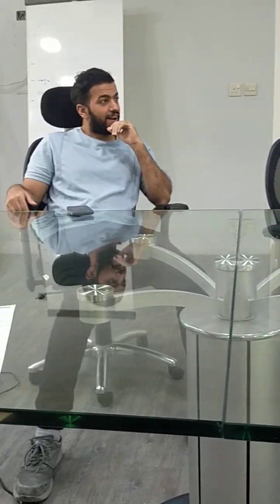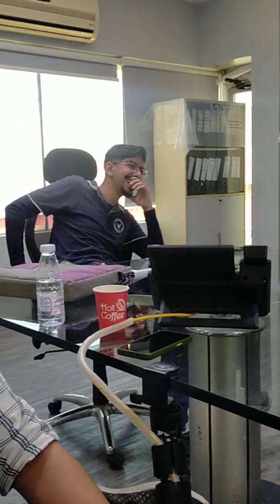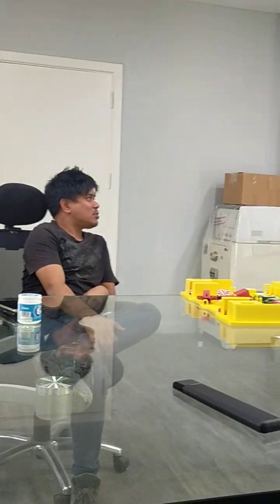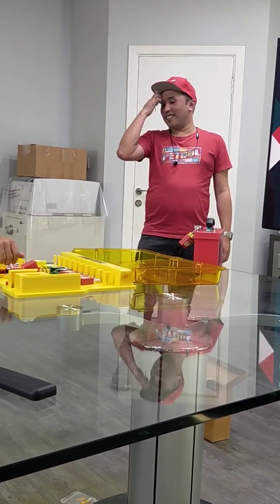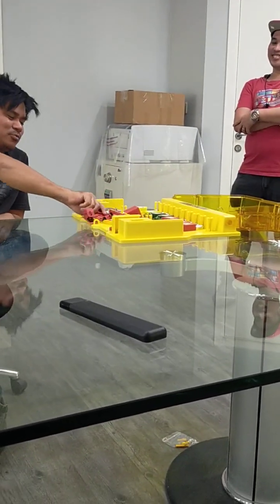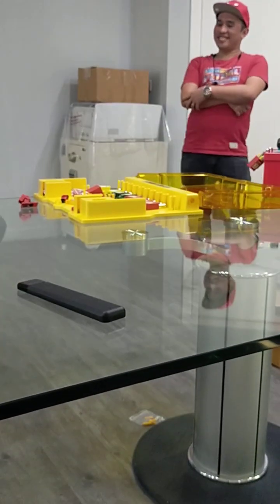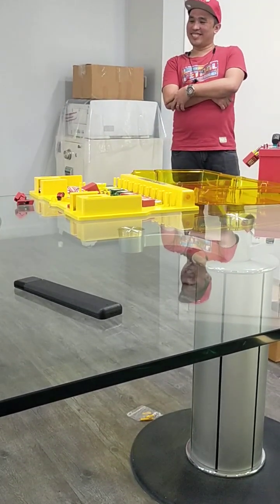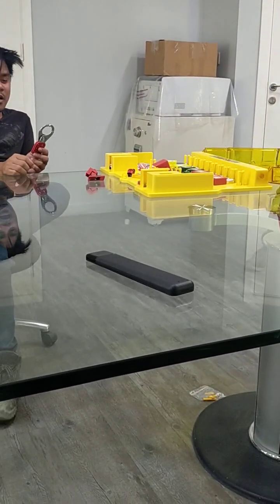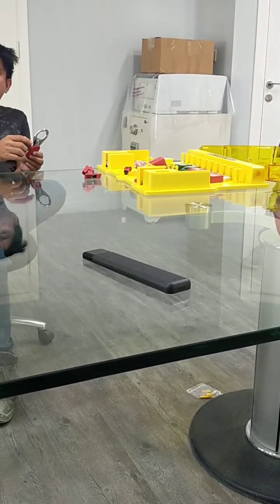Yeah, because the principle is we should have only one key. Because this is my experience. We put this one in the breaker side, to isolate the valve. All padlocks are there. Then my electrician is working there. He put his padlock. I'm his engineer in charge.